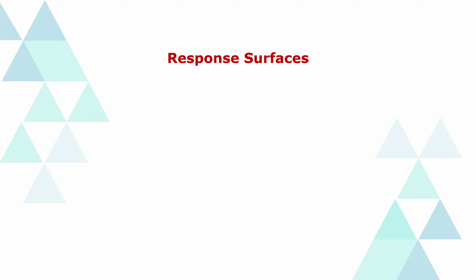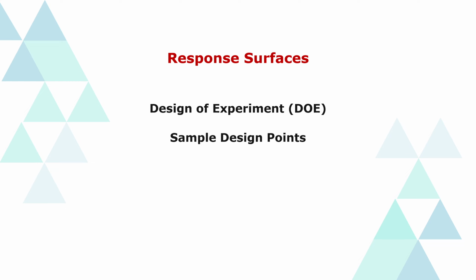Response surfaces are functions in which the output parameters are described in terms of the input parameters. Using the values obtained from DOE, they estimate approximated values of output parameters throughout the design space without needing a complete solution. In other words, several sample design points are defined as a design of experiment, or DOE. These design points are built in the range of the input parameter variations in which the values of the output parameters are obtained.